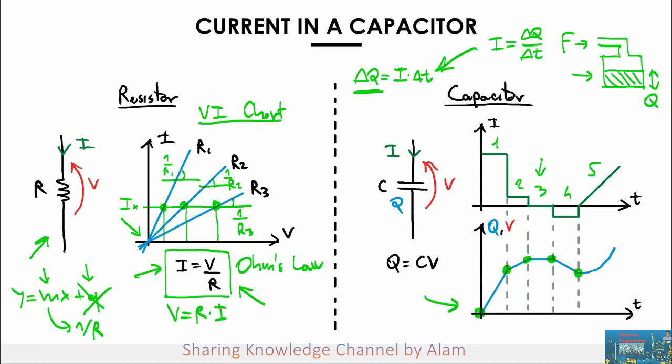I want to now make an important point regarding the state of charge of a capacitor, and it is something similar to what I said at the beginning, when I said that assuming that the charge at the beginning was 0 was a totally arbitrary thing, and I could have chosen any other value. That is true. And if you look at the charge evolution on the capacitor, you can notice one interesting thing. In a way, the charge in the capacitor is a sort of memory effect that the capacitor has on anything that happened previously to that point.